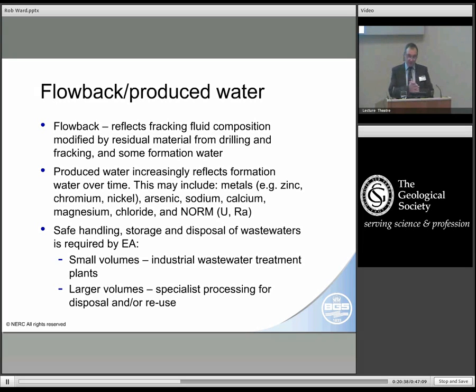And that involves the separation of the solid material, the processing of the liquid to enhance flocculation and precipitation of materials in suspension, and then treating the liquids that remain by processes such as industrial distillation, effectively, to ensure that there is further removal of the contaminants to produce a wastewater which can be released through a wastewater treatment plant or directly discharged to the environment if it meets the required standards.